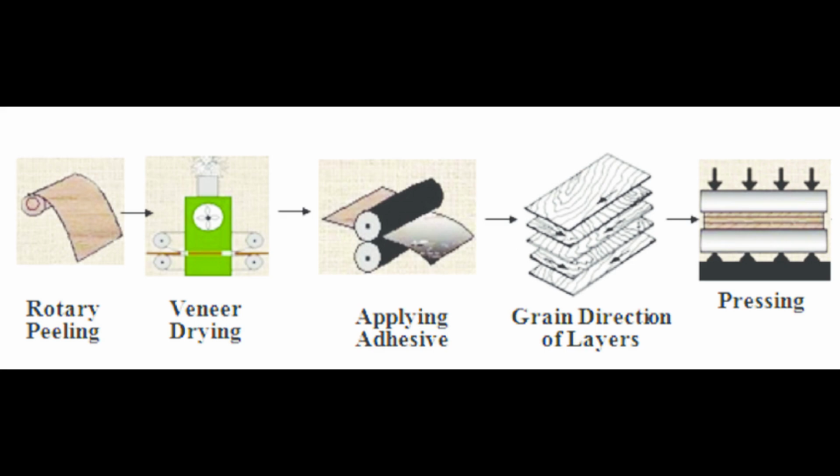The adhesives used in plywood have become a point of concern. Both urea formaldehyde and phenol formaldehyde are carcinogenic in very high concentrations. As a result, many manufacturers are turning to low formaldehyde emitting glue systems denoted by an E rating. Plywood produced to E0 has effectively zero formaldehyde emissions.